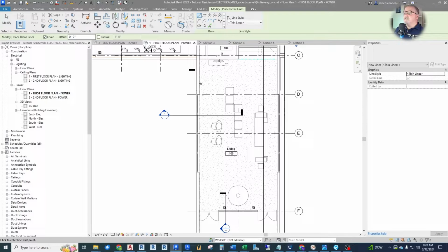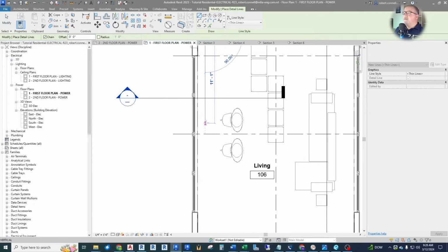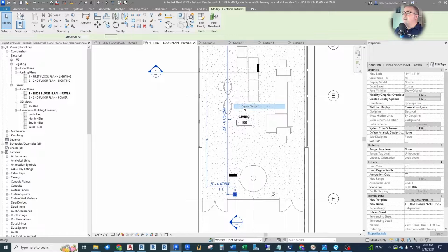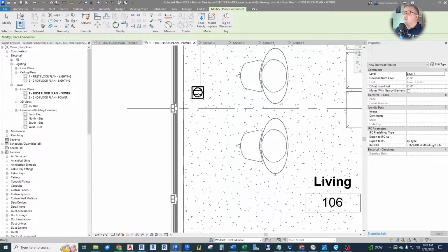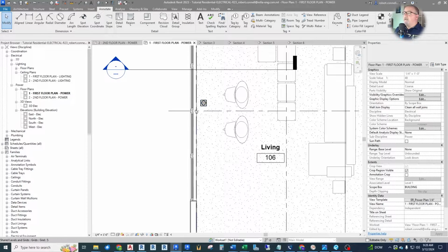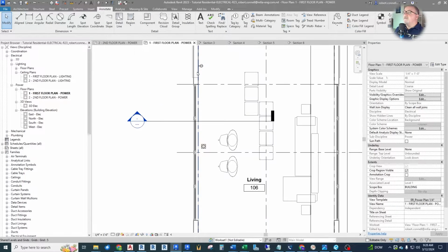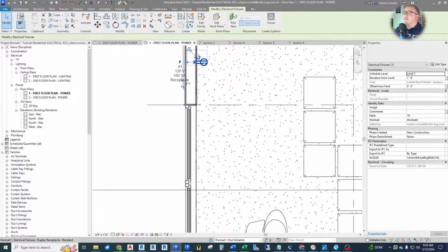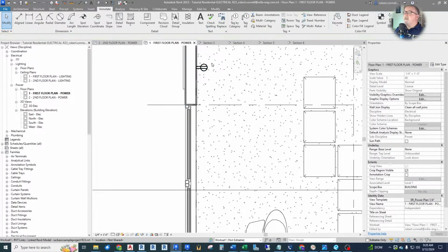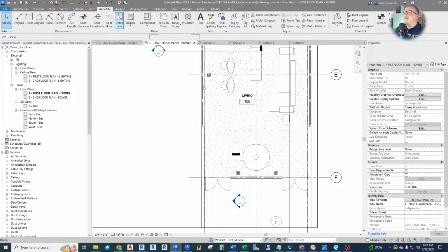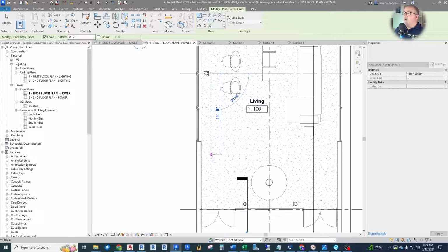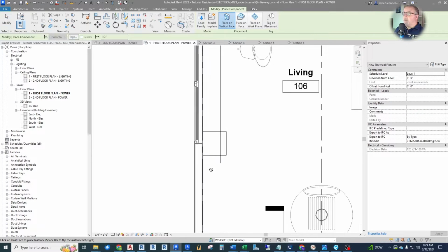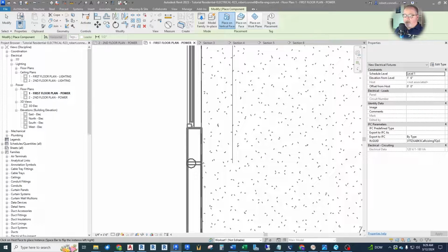Wrong, we need floor boxes. So 11.6 is a good, careful dimension. Get this down here. And if we want, we can line that up with that mullion and still be within our 12 feet. And we can move this a little bit because it was 11.6, but we're getting down to the inch here. And then what do we have from here? We can go 11.6 to that. And that truly is a wall. So we can create that on the wall. Not the, let's tab out. There we go.